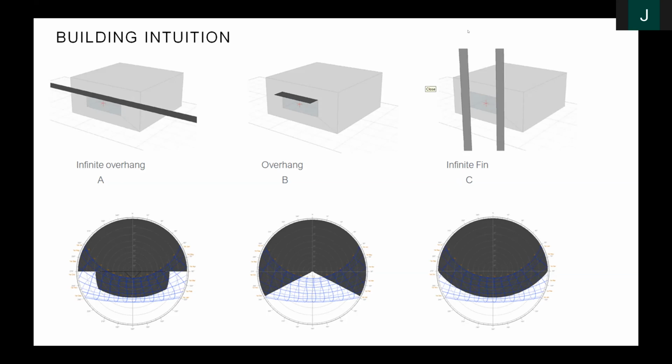C, yes, thank you. An infinite overhang looks like C because here on the horizon, the overhang starts and it covers some of that south-facing sky all the way from one horizon to the other horizon, projecting out a certain distance which corresponds to the profile angle, right? You're using a profile overlay here to determine what curve this shape would take.